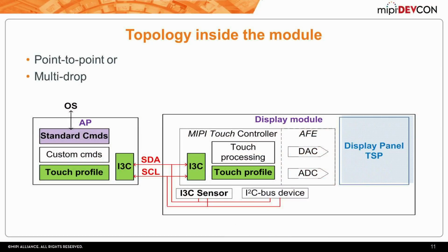So again, here's the touch panel. Here's the analog portion, and so if I was only going to implement an AFE as a controller, in general, I basically have all of this. There may be some additional supporting digital, but this right here then hooks directly upstream to the AP. If I'm a traditional controller, I add on this additional block, which now manages the touch processing as well. And both of these are transported back to the MSM.